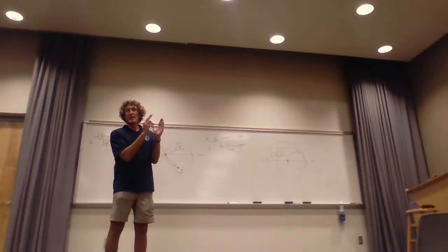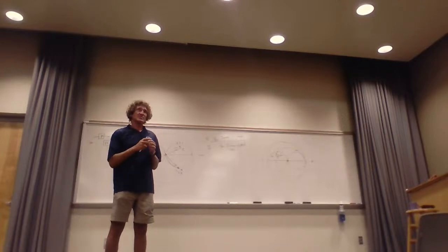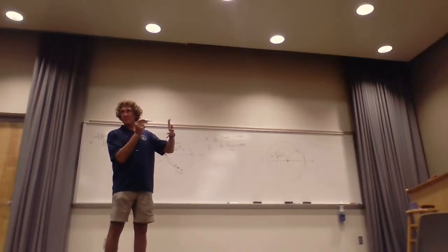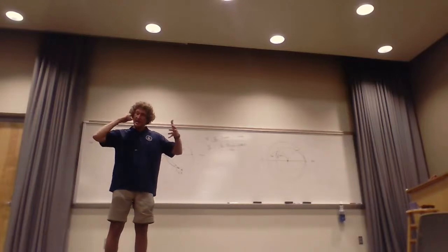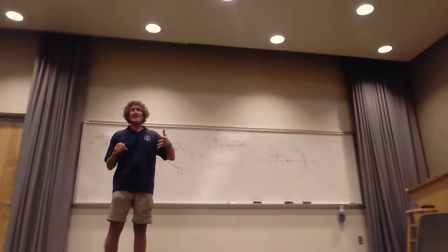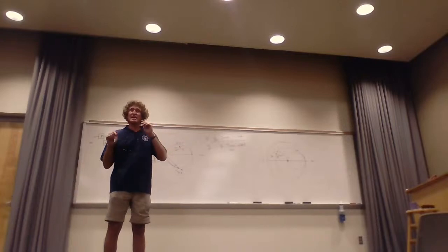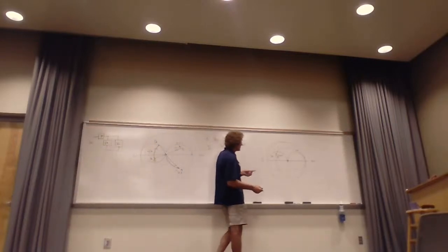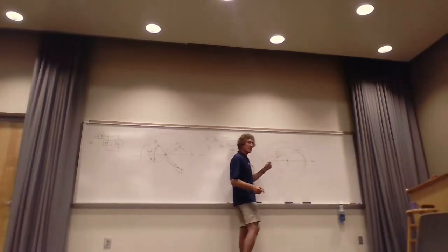Y'all follow me? But when you're dealing with microwave circuitry, it's very possible that you can feed an actual BJT amplifier with one of these things. You need an L section matching, and you're going to have a microwave link there with DC bias. So an inductor in series is good. That's my take.